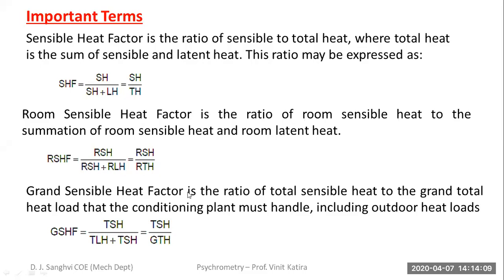Now in your normal residential applications, there is no such requirement of dedicated recirculation of air. Now when I say recirculation of air, the only purpose is to ensure that the oxygen levels are maintained in the safe zone as recommended by ASHRAE.